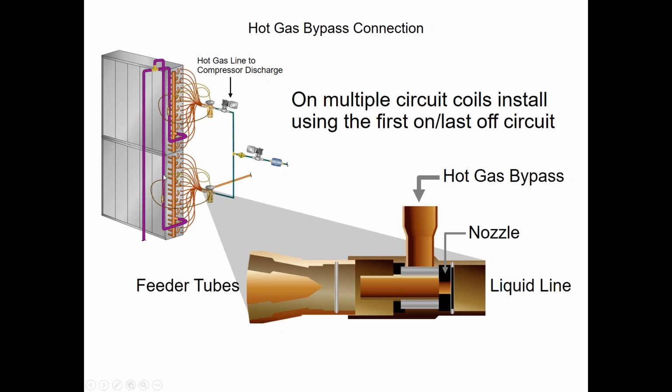Now you may have a couple of intertwined coils where we have to deal with the phase split issue, because remember, we always want full phase typically in any DX cooling application, especially in VAV and VVT applications where we have varying airflows and things like that. And the reason behind that is a VAV unit is always going to control to a discharge temperature, okay?